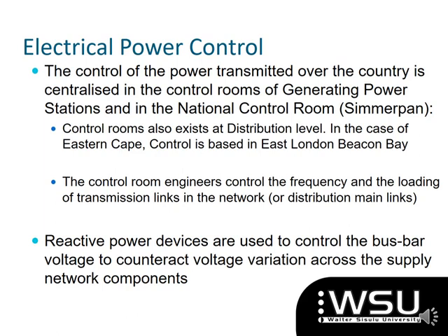In the case where the country is back in load shedding again, it basically means that the power being generated, even when they include the peak power stations, which are the stations that only come on board when the need arises, is not enough. They're not always running. They only come in when the load is getting bigger than your generating capacity. So with load shedding, it means even if those have come on board, because load shedding usually happens due to unplanned maintenance or an emergency in one or two of the generation power stations, we now have an imbalance.